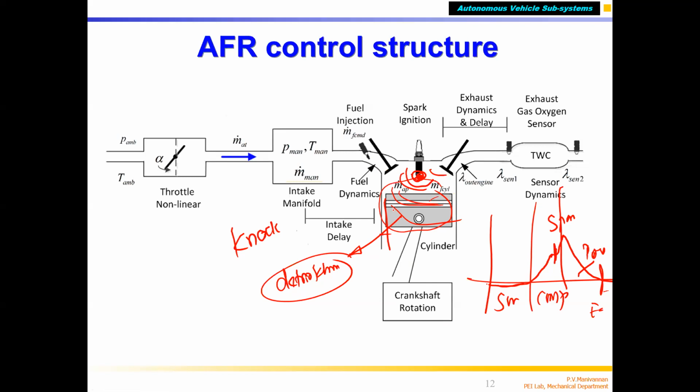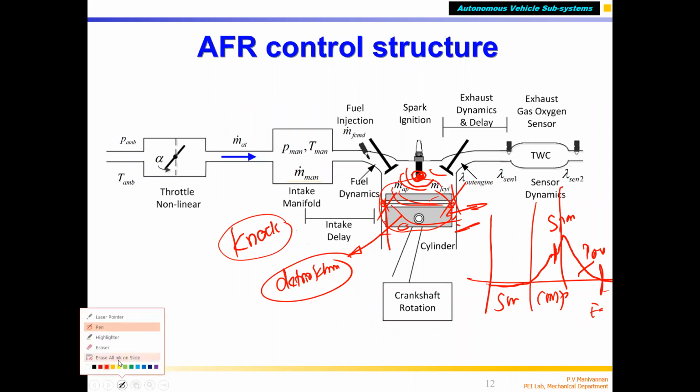We know that if you have multiple hot spots, because I will tell you what a hot spot is, then fuel can burn instantaneously. It is called detonation, because of knocking. Knocking means the cylinder will vibrate violently, and the engine cylinder can break. If you run your engine in knocking or detonating condition, the engine will fail. So you should not run the engine at knocking condition. That is a separate area. If you are ICE engine people, you will know.